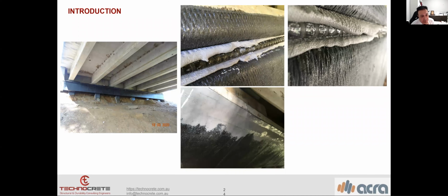It shows the FRP rod, which can completely lock the CFRP wrapping into the substrate. And in the middle bottom one, you can see the finished work of the anchorage system.